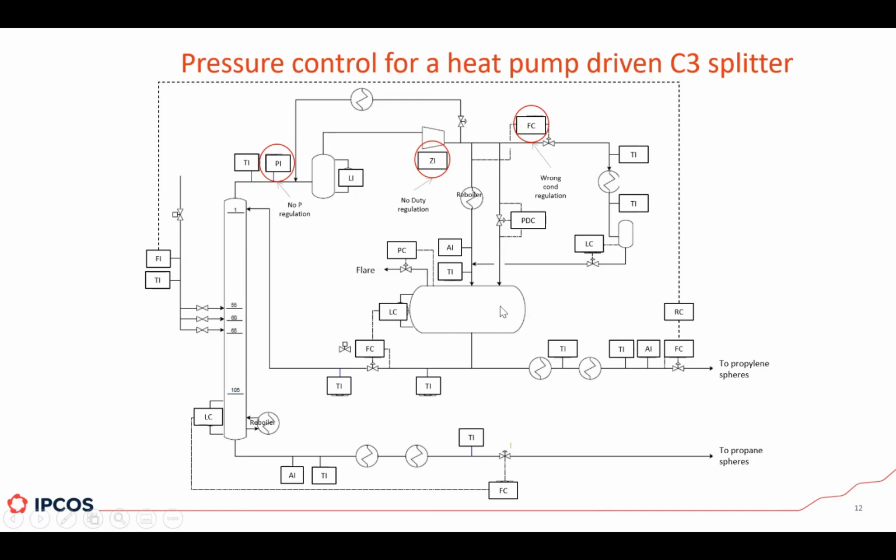So what happens here is that since the heat generated, or the heat transfer in the top is also the same one as the one used for a boiler, then all these vapors condense, and most of those vapors will have to go back to the column again as reflux. So that creates a direct interaction.